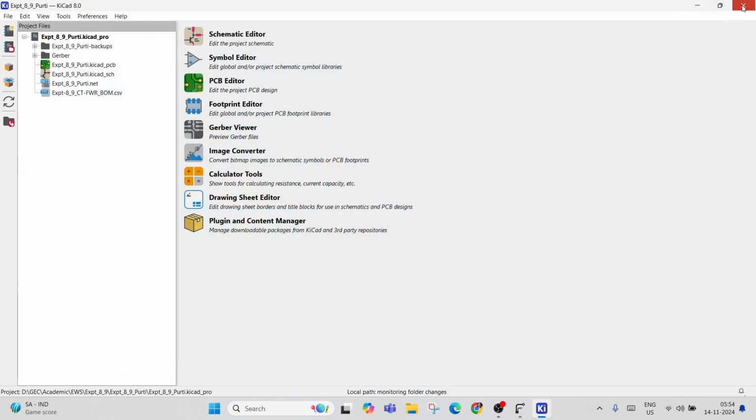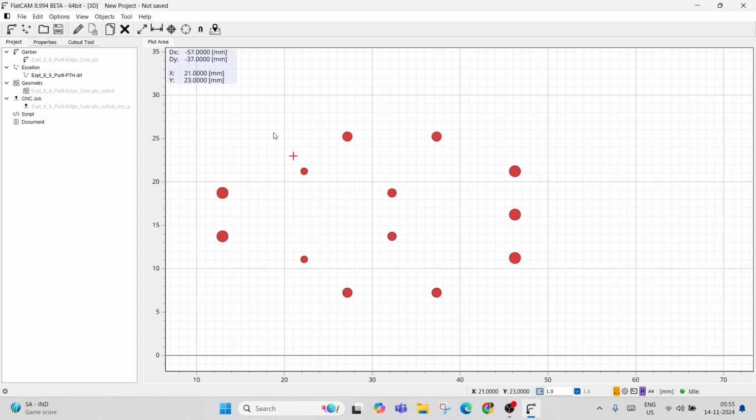Once that is solved, now that you know what the problem is, we will not get into tool change for various pin sizes or hole sizes. We will just set the tool diameter to 1.415 mm, which I have, and I will change all of these hole sizes to that.